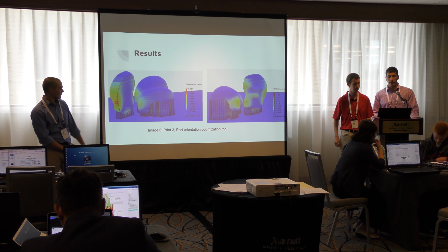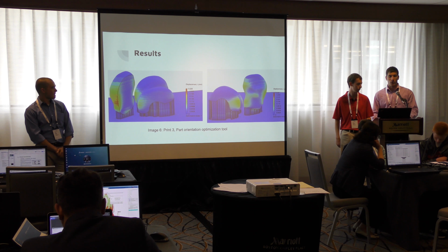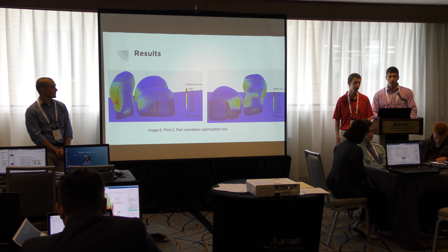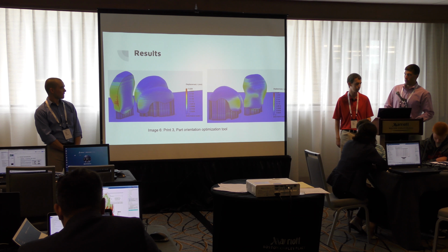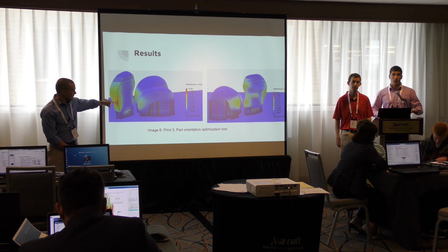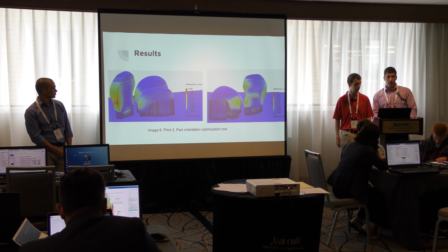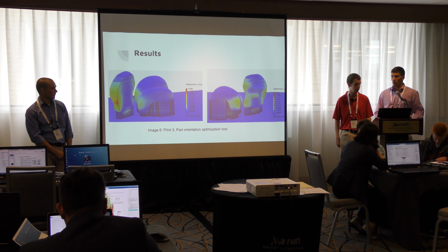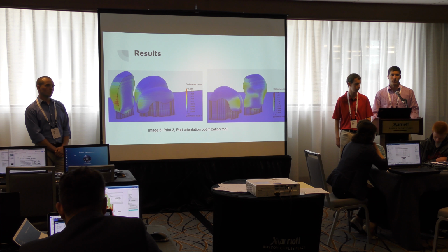And then along with that, when we did this, it helped remove a lot of the displacement that we had, and we believe this is due to the fact that our printing surface area is decreased in the horizontal plane. The leftmost picture, again, whenever we printed it laying down, we had a lot of distortion in the center of the tibia. And in this, we dropped the distortion all the way down to 0.22 millimeters, so almost a quarter of what the distortion was in the original laying down, which seems probably the most basic way to print it.